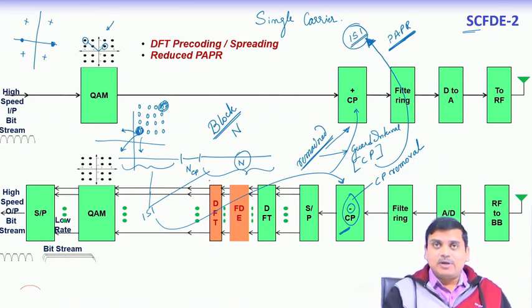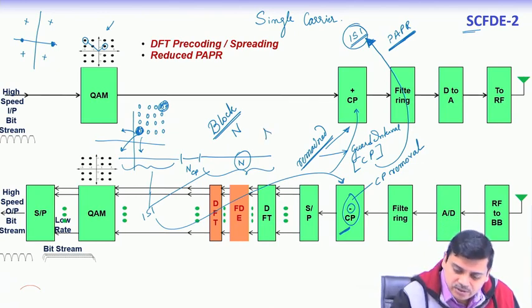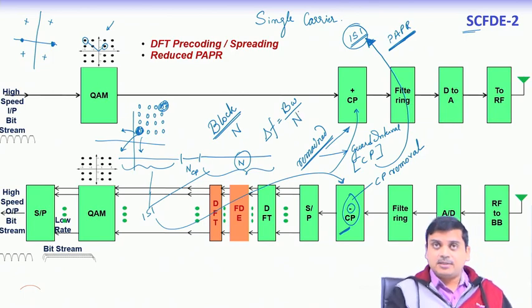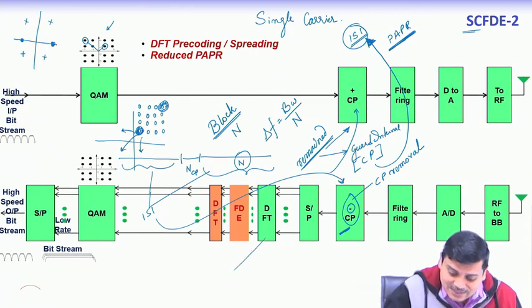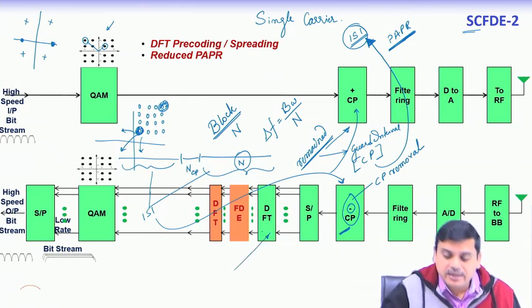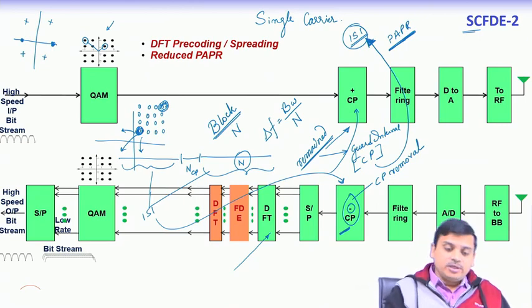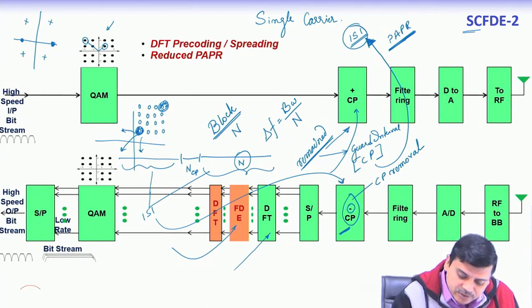So, what does that help us? Every subcarrier, now we are seeing a subcarrier, although the subcarrier was not present, but we are seeing in the frequency domain with a certain resolution, and the resolution that we see is equal to the bandwidth of the system by n, that remains. So, if we can have n very large, now look at this n, one can choose independently, one need not be constrained because the transmitter does not have any value of n. So, this can be chosen independently with any finite resolution that one thinks of, and one can apply this frequency domain equalization.